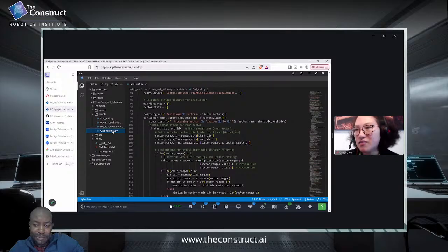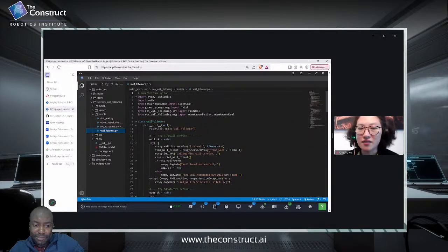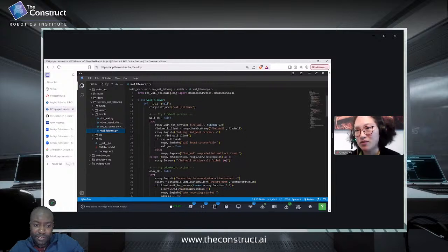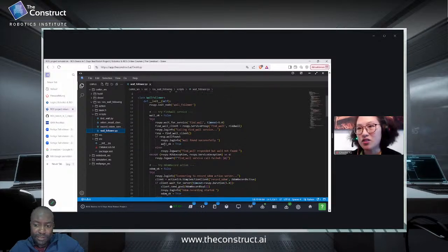I added some error handling for safety in the wall following. If it detects any obstacles in the front, it will turn a sharp left. If the robot keeps doing that, obstacle, sharp left, it would eventually be following the wall, because we have a very simple environment. So that's basically my way of error handling. All right, I see.